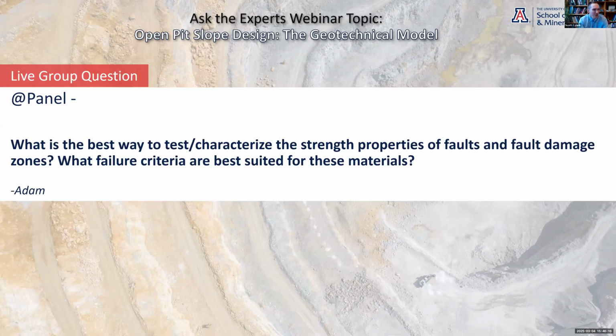And then in the laboratory, you'll want to do your characterization first. So you'll want to do your Atterberg and your sieve before you do the shear test. That way you know about what the plastic limit of your material is, and then you can base the moisture content for the test on that. Because generally, if a fault zone has access to moisture in the field, its in situ moisture content is probably going to be somewhere around the plastic limit of the material. And so you'll want to make sure that you test it at that in the laboratory and don't test it on the dry side.